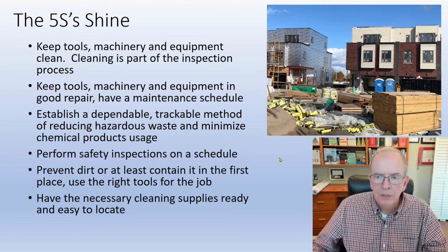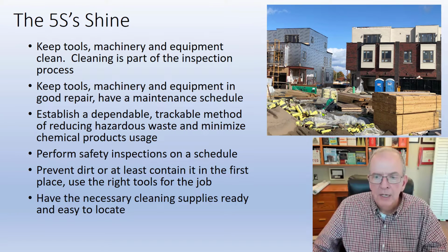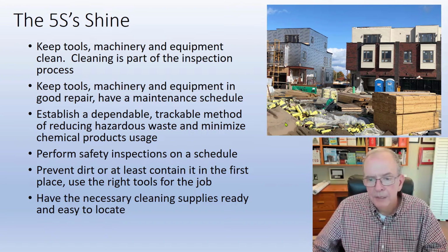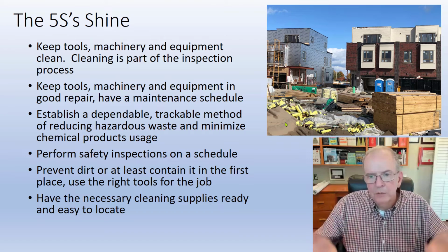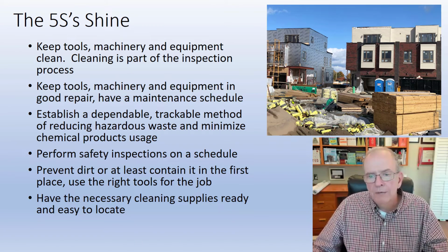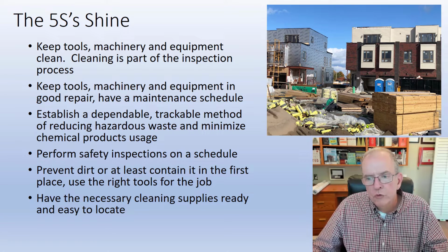So I'm talking about this construction site here. I noticed that when the masons were doing the work, they had their masonry cement, they have their sand. They cover the sand sometimes, but I'm not sure that they were, so that the rain doesn't absorb soluble salts from the ground and get efflorescence and that kind of stuff. They've got these bags just strewn about.